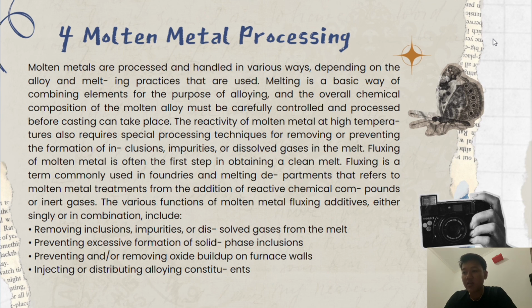Removing unwanted impurities or dissolved gas from the melt. 2. Preventing excessive formation of solid phase inclusions. 3. Preventing and removing oxide buildup on furnace walls.